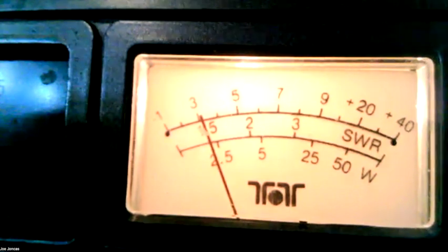Okay, 5 and 8, what does that mean? That 5 and 8 means I've got a pretty nice signal. So it's okay, easy to copy. First of all, the 5 means that it's very nice audio, very, very clear. And then the signal strength, I can get off my S meter on my radio, and I gave them a 5 and 5. So that's a decent signal report. If you told them it was a 5 by 9, that would be a very strong signal.